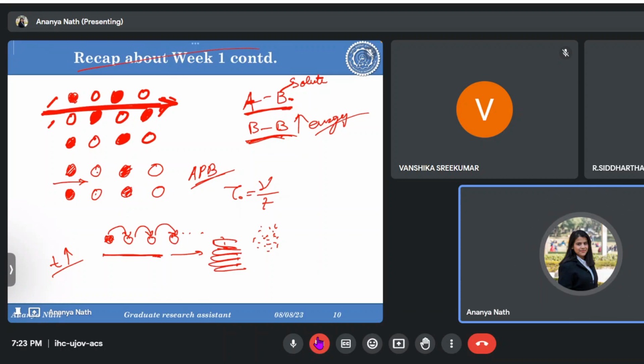So it's a complex scenario, but if you imagine it this way: the dislocation is moving and the solute atom is trying to catch up, and then the dislocation makes some other situation where it again finds it difficult to move farther, and in that time the solute atom has moved and has achieved an equilibrium position where it has come forward to the dislocation, and a second phase is precipitated, or some clustering, or the atmosphere is made, so it will be easier for you.